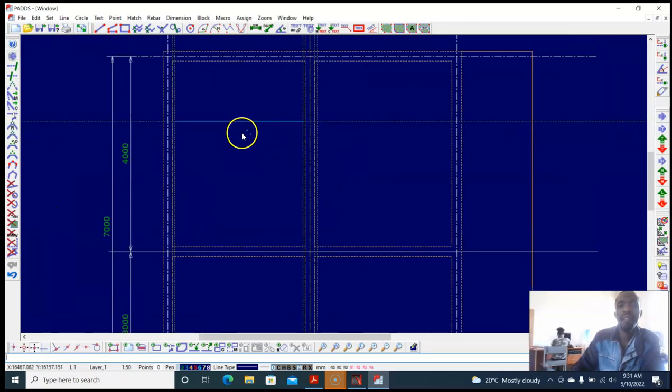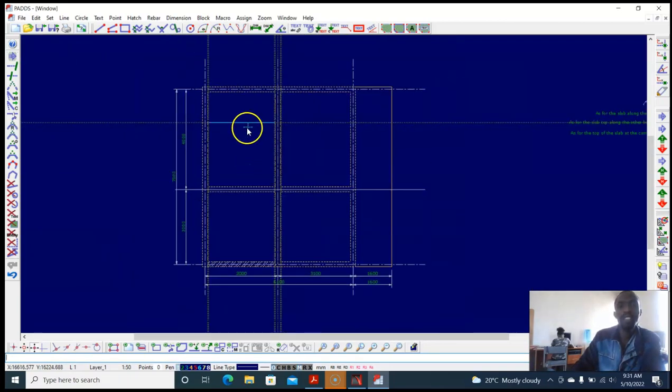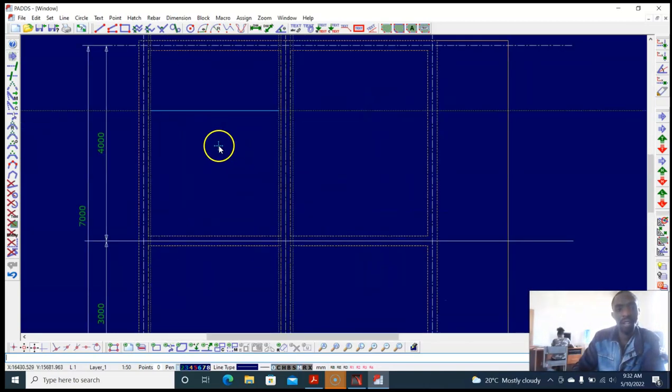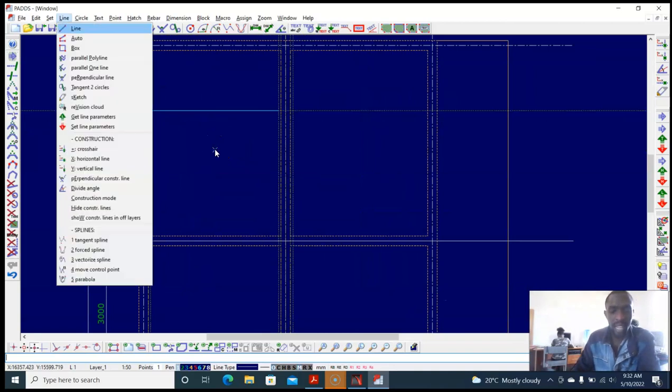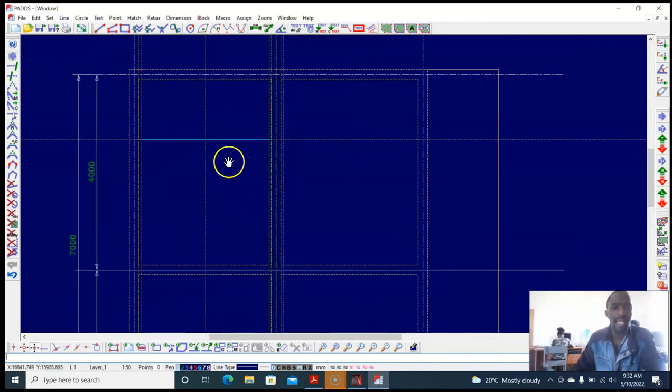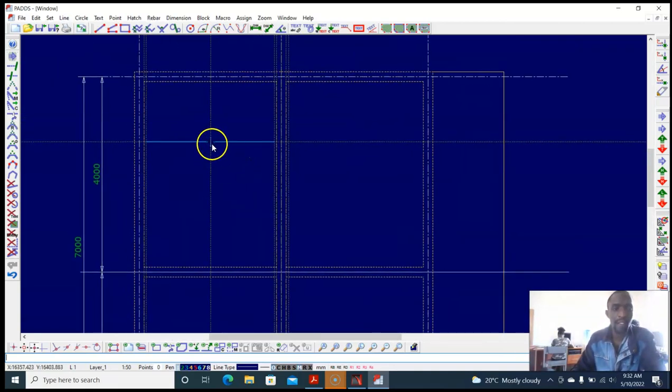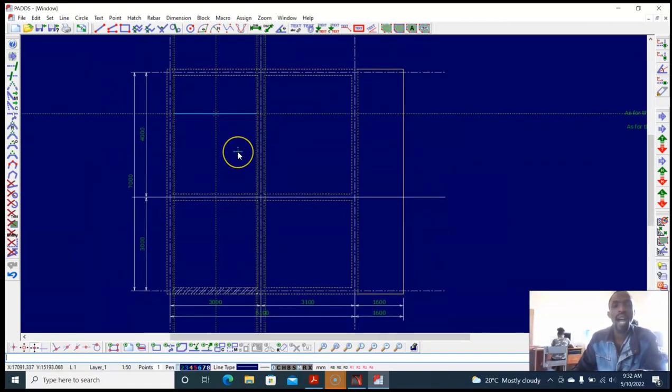So beautiful. We have reinforcement at that place. So let's say this reinforcement, we require it all the way. So I'll click there, type LY, and pick that reinforcement. To distribute the reinforcement, let's work with R5 to distribute the reinforcement all through.